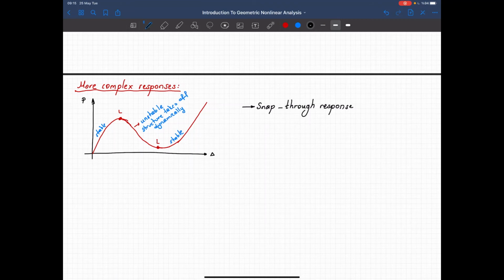Where do we see this type of response? Basically, one example is the buckling of shells. You can actually observe this. Take a Coke can, press from the side, and then you will see that it flips and it catches another equilibrium path and starts to carry the applied pressure that you give with your finger. Okay, so if you just draw it, initially it was like that.